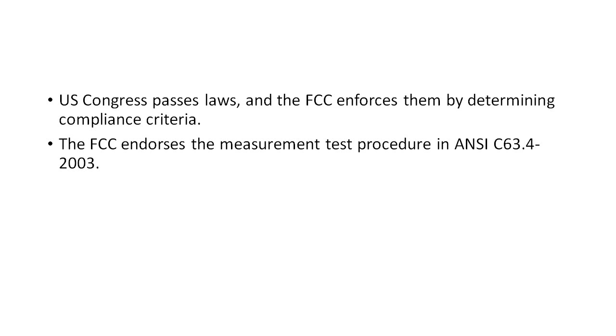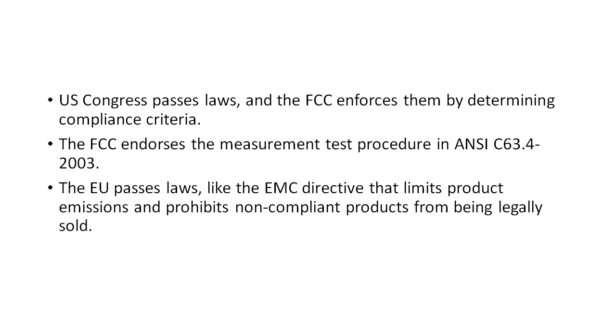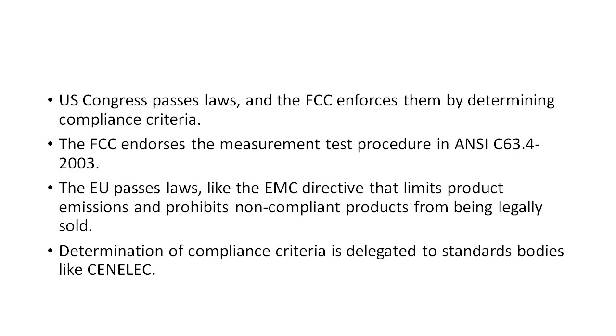To compare this with Europe, the European Union makes EMC compliance the law by passing the EMC directive. To quote directly from the 2004 directive, it says that the design and manufacture of equipment is subject to essential requirements in relation to electromagnetic compatibility. Those requirements are given technical expression by harmonized European standards to be adopted by the various European standardization bodies: European Committee for Standardization, or CEN, European Committee for Electrotechnical Standardization, or CENELEC, which we just covered, and European Telecommunication Standards Institute, or ETSI.